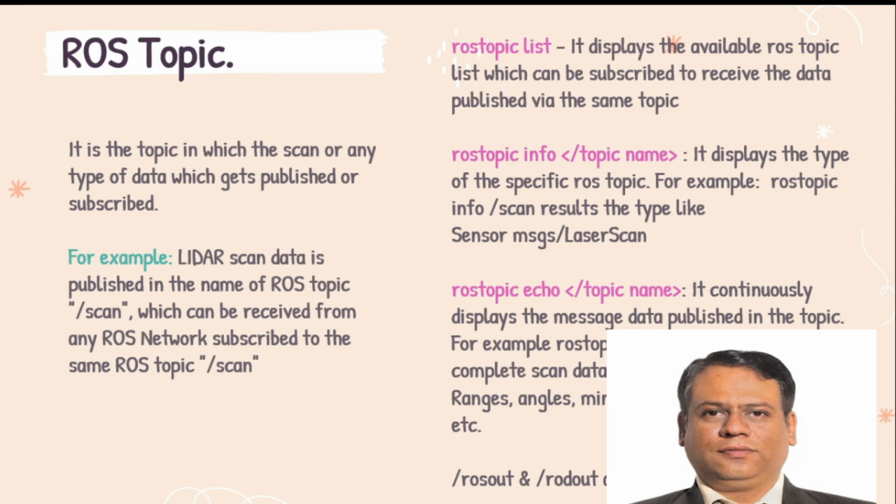So for example, ROS topic info /scan will give you the results, what kind of data it is. It is a sensor_msgs laser scan message, which I have described in this presentation. So ROS topic info /scan gives you the information like sensor_msgs/LaserScan. So it is a kind of data about the laser scan.